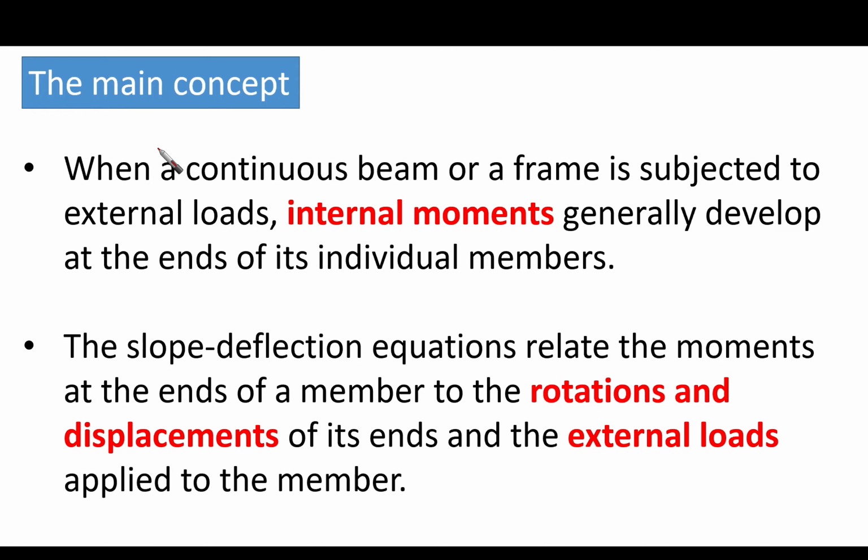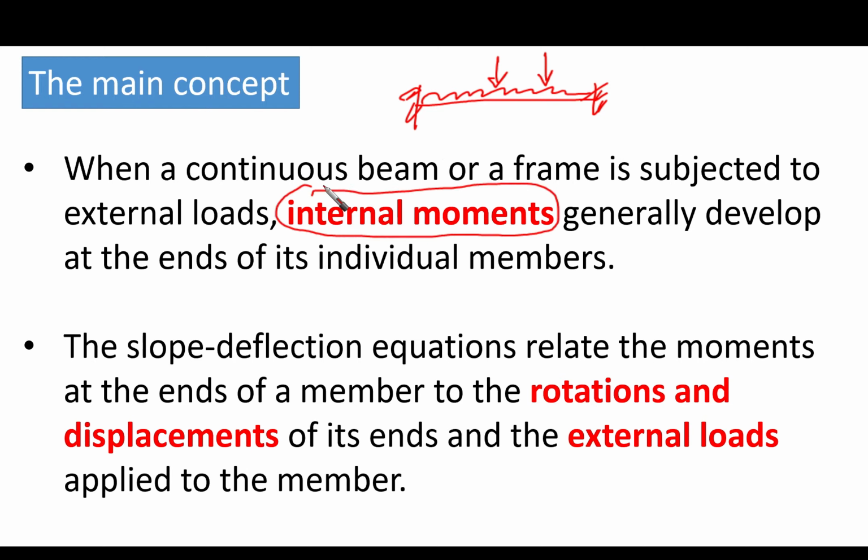So now let's talk about the main concept of the slope deflection method. When a continuous beam or a frame is subjected to external loads, internal moments generally develop at the ends of its individual members. That's very true. Whenever we have any member and we have any load of any kind, whether it is a distributed load or a concentrated load, due to these external loads, internal moments are going to be developed.